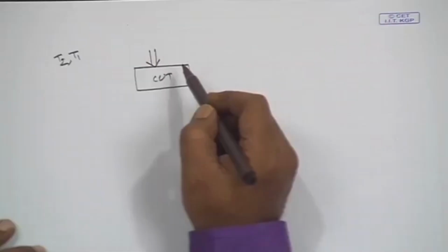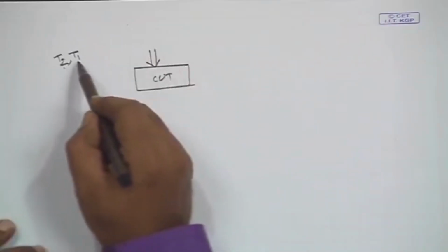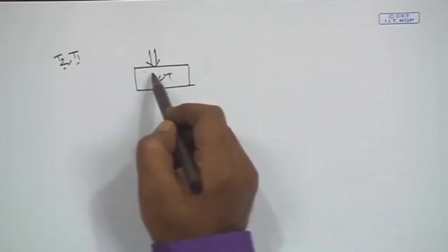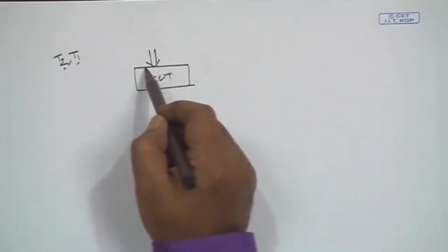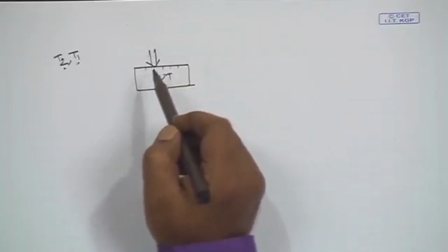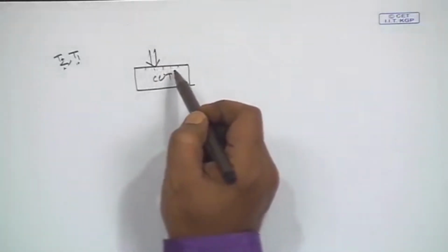Now, if we can ensure that between T1 and T2 many bits are not changing, then it is possible that many of the gates which are getting input from the primary input will not make a transition, and subsequently the gates at successive stages will also not make much transition if the first level gates are not doing transition.